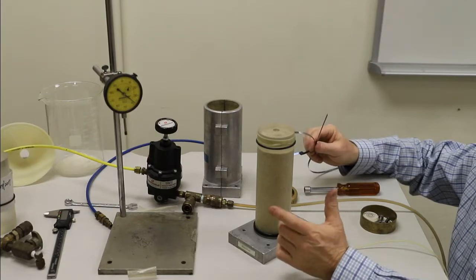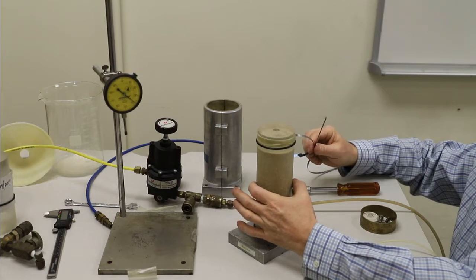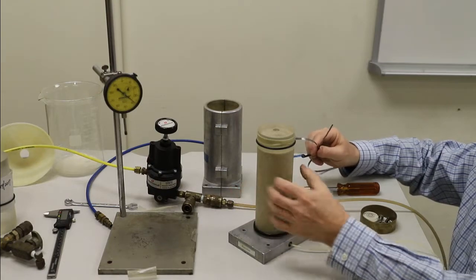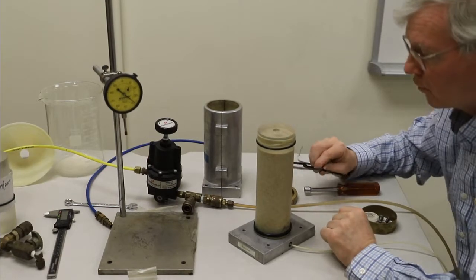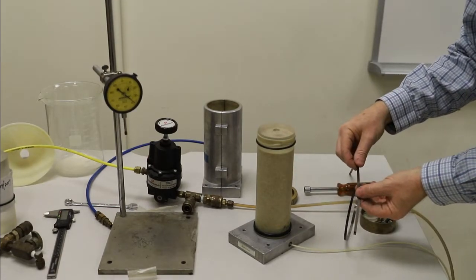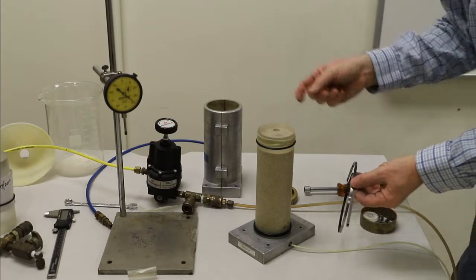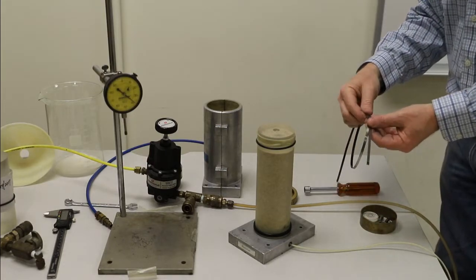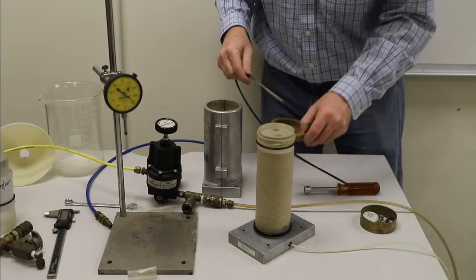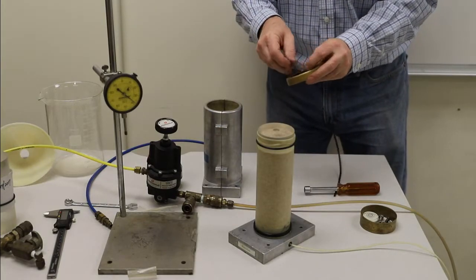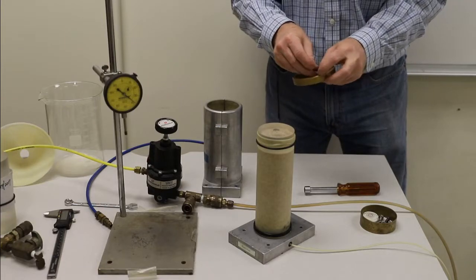Whereas if we had calipers and we happened to measure the long axis of the ellipse, that would be an error, assuming it was a circle. Of course, the way it does that, it just factors in a value of pi. It's measuring the circumference, pi d, and you divide by pi and it gives you the diameter. So, if you get the chance sometime, you'll know how a pi tape works.